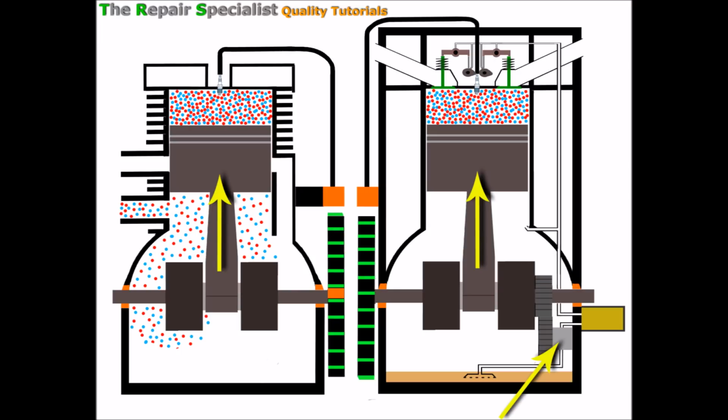So I've been saying that the oil pump creates all this flow, so it's creating all this energy. So where does it get its energy from? And it does so from the crankshaft. It's geared directly from itself to the crankshaft. So every time the crankshaft turns, it turns the gear of the pump, and that creates the turning motion inside the pump for all that movement.